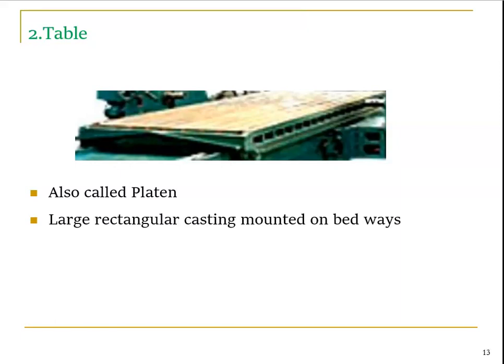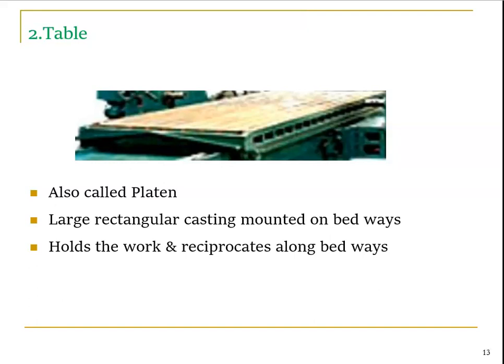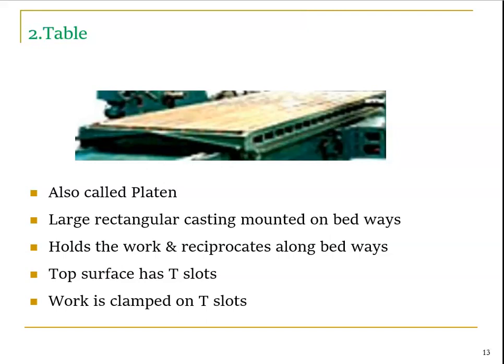Large rectangle casting mounted on bedways holds the work and reciprocates along the bedways. Top surface has T-slots. So the table has T-slots. You can connect using T-bolts or use a vice. Work is clamped on T-slots.